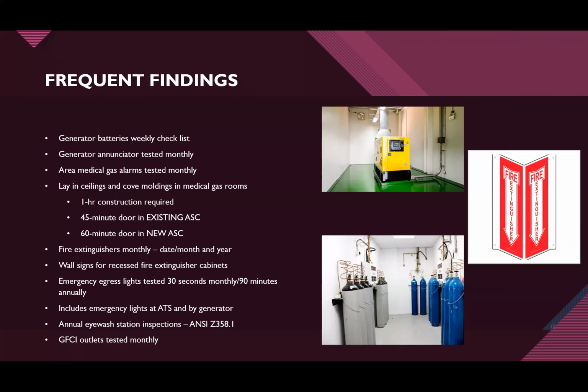And so the question that came in is, I have an older area alarm and it doesn't have a push button. Do I need a new panel? And the answer is no, you do not. If you have an existing system without a button, you can continue to use it as long as the authority having jurisdiction, whoever does your survey, says you're still good to go. But you want to ensure that those area alarms are well documented on your annual med gas inspection.